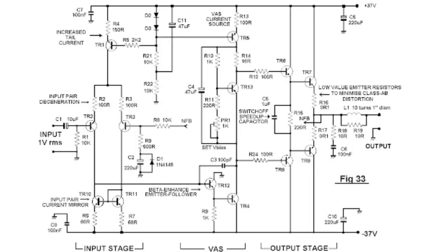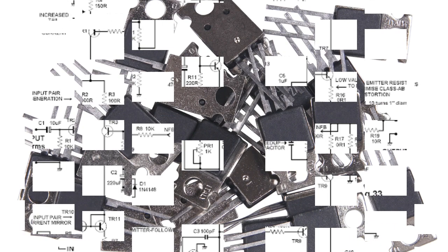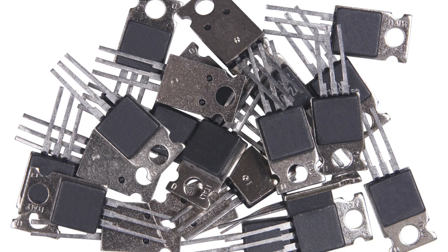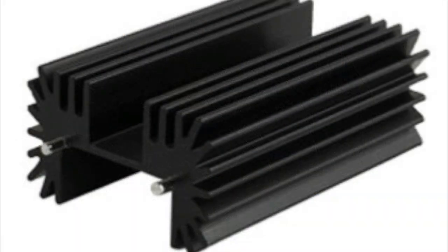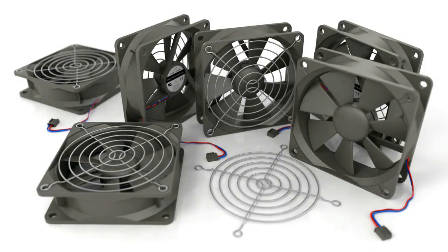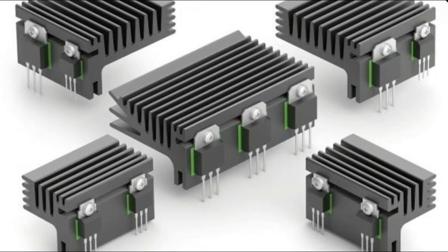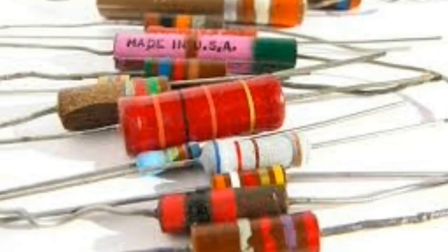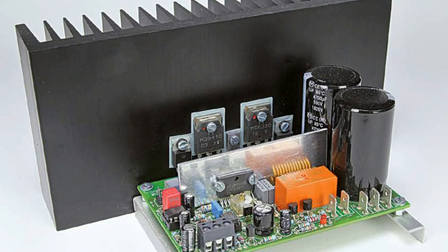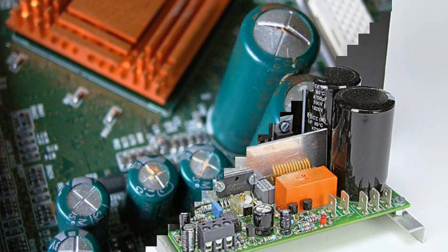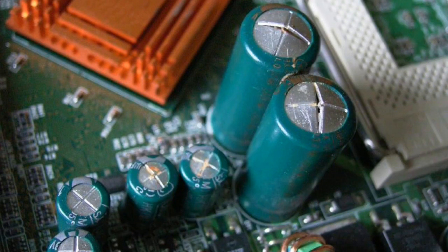Poorly designed amplifiers, especially Class A types, may require larger power transistors, more expensive heat sinks, cooling fans, or even increased power supply size required to provide the additional power dissipation required by the amplifier. Electricity converted to heat from transistors, resistors, or any other component will render any electronic circuit inefficient and lead to premature failure of the device.